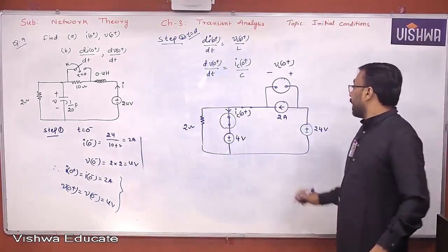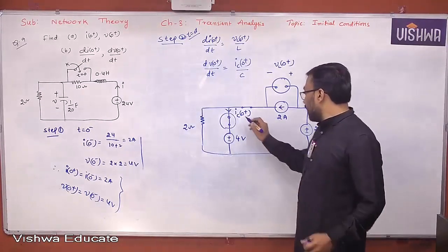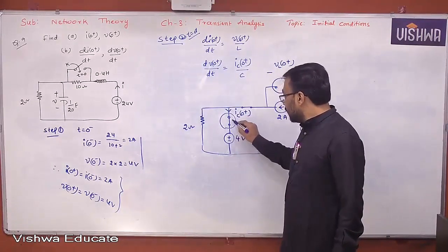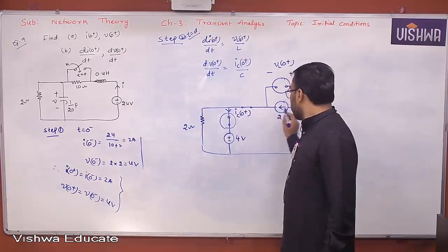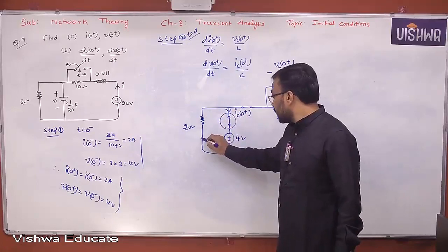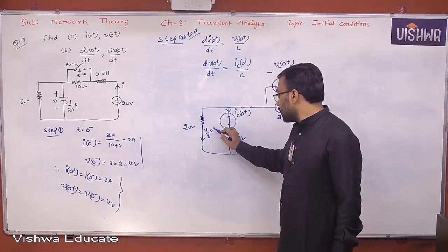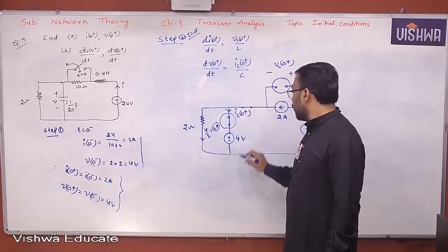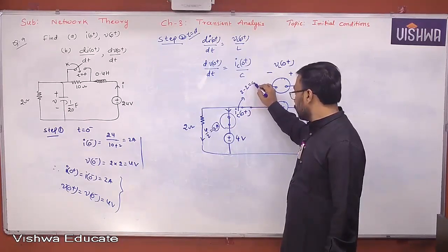Okay, now tell me, look at this, all of you. The current can be determined here. Current through any path, when there is no resistor, you are supposed to apply Kirchhoff's current law, yes or no? So what is the current actually? 2 amperes. What is the current here? The same voltage will appear. Actually the current flowing here is 4 divided by 2, 2 amperes. And 2 amperes is entering, 2 amperes is leaving. Therefore, this current will become 2 minus 2, 0 ampere.